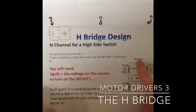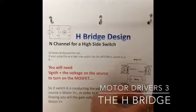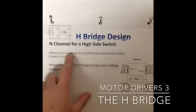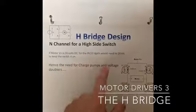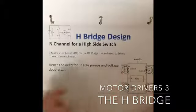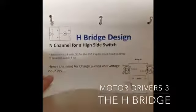Alright, so motor voltage is the rail. See where we're going here? If the motor voltage is 24 volts DC, and the gate threshold would need to be at least 26 volts. Hence, you'd need a charge pump to get this guy to turn on. You need to go above that voltage.